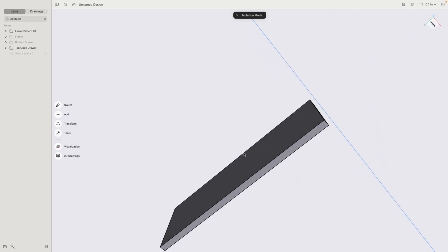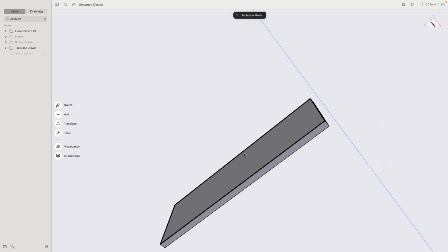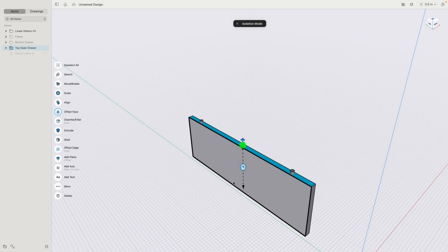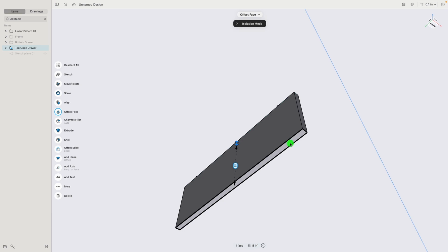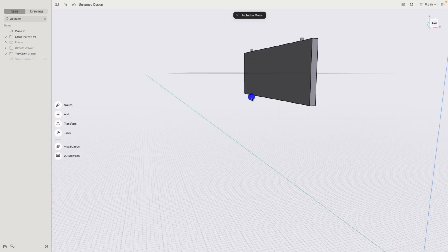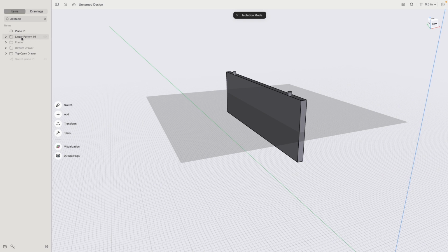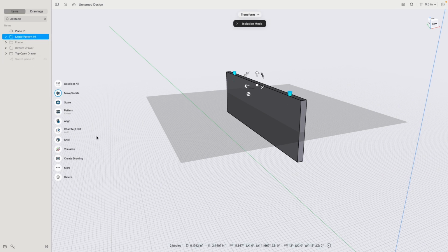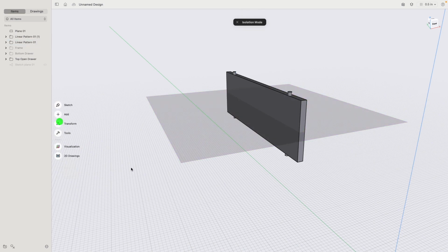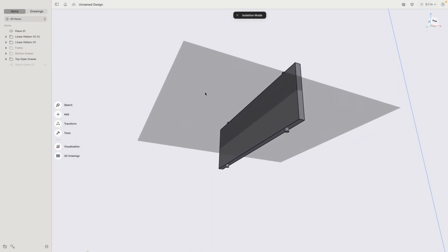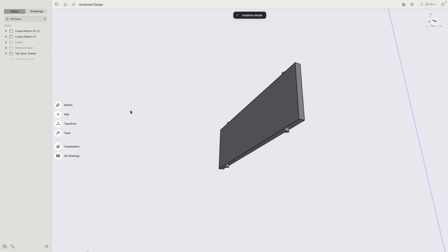I would like to have now at the perfect position also the 2 dowels at the bottom. This is very easy. Check this out. I select the top and the bottom face, then create a construction plane at the midpoint. Select my 2 wooden dowels, go to more union, click this plane, done. There we are. This construction plane I don't need anymore.